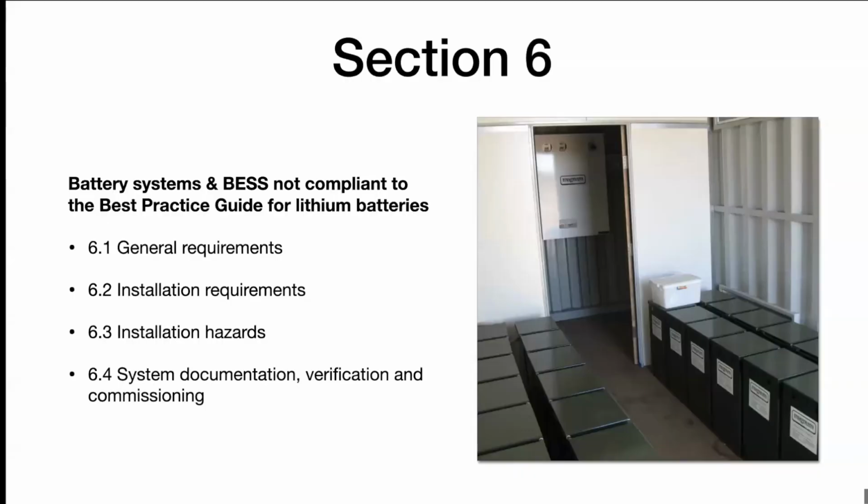Yes, from Jeff: does a pre-assembled BESS always include a PCE? So a pre-assembled BESS, because the last S is system, means there are components that supply energy from a battery system. And so it could be, I don't know of any, but it could be a DC output as opposed to an AC output. Maybe it might be a pump controller or something. So it's possible to have a BESS that is not an inverter, but I don't know of any yet.